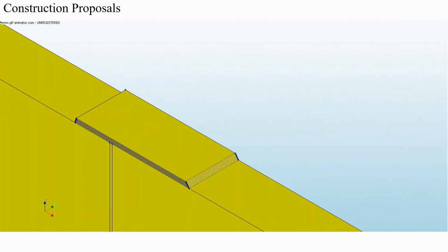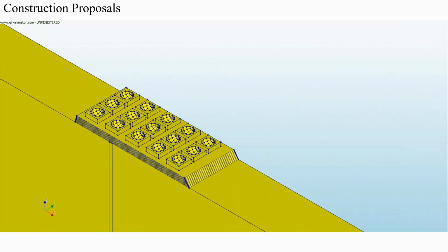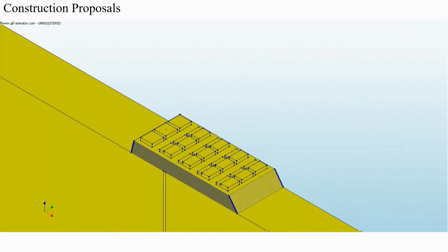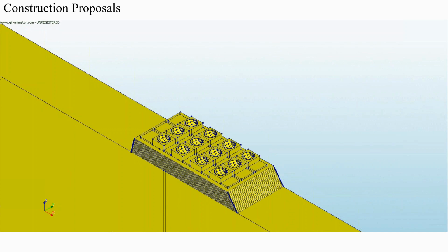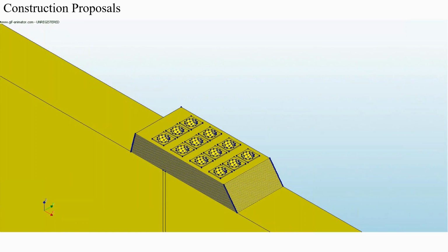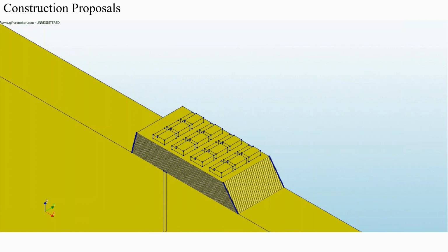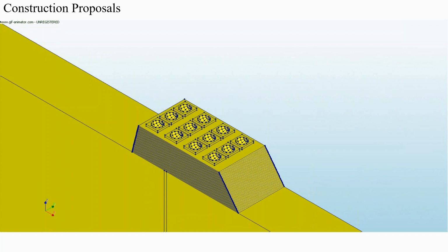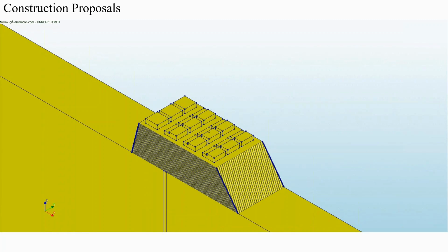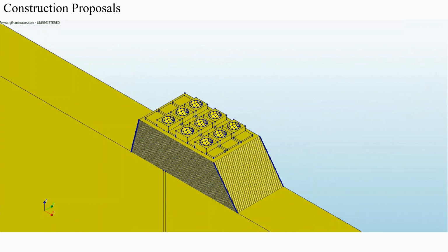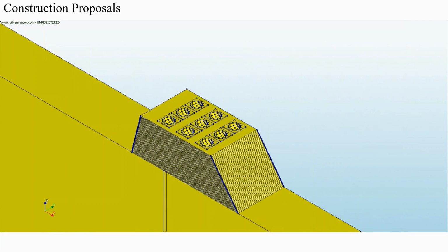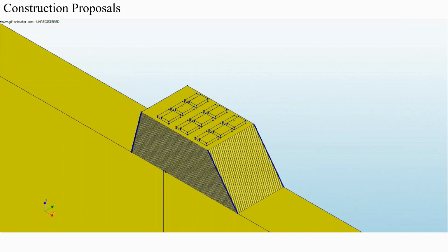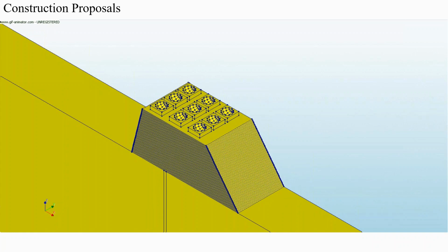In order to simplify the process of making bubbles inside the dam, cubic precast blocks with inner spherical voids are precasted and placed in their location, as you can see. In this method, the roller compacted concrete is compacted using a traditional roller compactor. The use of the precast concrete blocks will decrease the required cast-in-situ roller compacted concrete by around 30%. That would increase the construction speed of the dam.